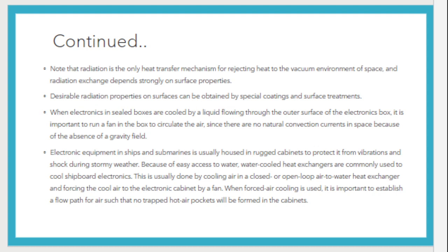When electronics in sealed boxes are cooled by liquid flowing through the outer surface of the electronics box, it is important to run a fan in the box to circulate the air, since there are no natural convection currents in space because of the absence of a gravity field.